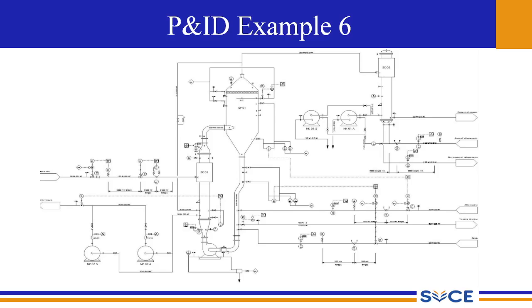Then all these major equipments have a particular naming convention, and all the temperature transmitters and pressure transmitters have a certain naming convention. We have to follow the naming convention and give the corresponding legend, and we have to look at the various connectors in the process flow sheet and the P&ID diagram, because those connectors will represent the continuation of the P&ID to the next section.